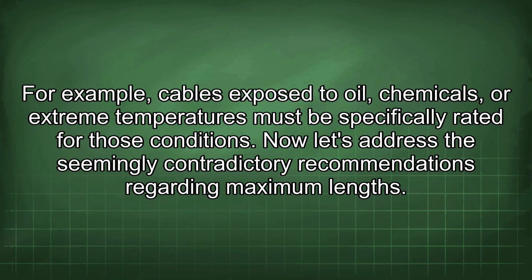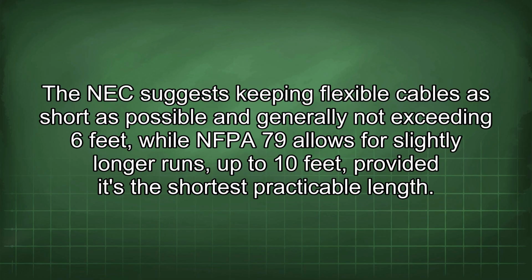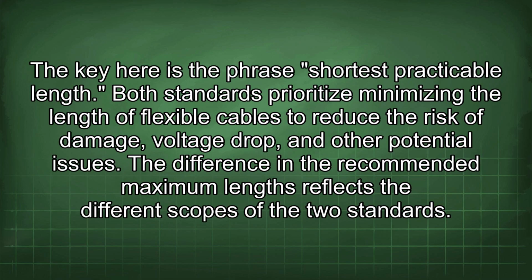Now let's address the seemingly contradictory recommendations regarding maximum lengths. The NEC suggests keeping flexible cables as short as possible and generally not exceeding 6 feet. While NFPA 79 allows for slightly longer runs, up to 10 feet, provided it's the shortest practicable length. The key here is the phrase shortest practicable length.